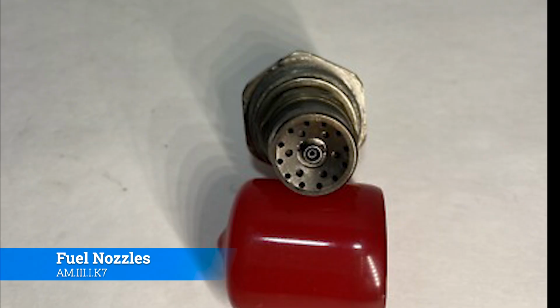This, based on the design of the engine and the design of the combustion chamber, has to be just so. It has to be exactly right. If it's off a little bit, the engine won't run right. You could damage the engine. It may not run at all. So one of the things you're always going to be looking for is making sure that the spray pattern is correct. The way this particular spray pattern works, it's going to create a big circular pattern, and inside it you're going to have multiple levels of ports that also spray fuel simultaneously. So you get a nice cone of fuel that mixes with the air and then gets ignited.